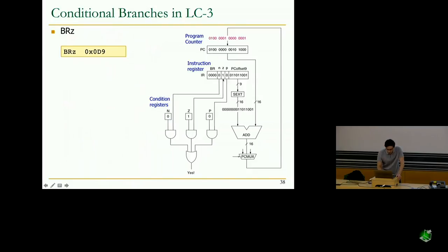So what we are doing with these 3 AND gates and this OR gate here is comparing these bits in the instruction with the condition register. As you can see, the result of this operation is 1. So the branch could be taken. Again, when are these 3 condition registers written?